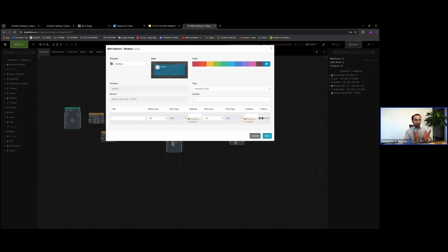So you must know all these technical details. You must have all these technical points. After that, you will understand what your Modbus device will provide and what you need to control the Modbus gateway. So you will ask the Modbus providers, the Modbus manufacturer, for the register table.